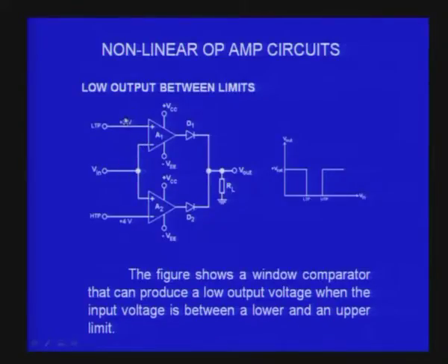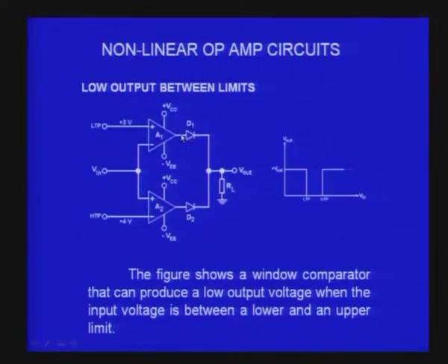Here this 4 volts is more than 3 volts, therefore it will be minus at the output in this A1, but minus here will make the diode open. It will not conduct, because diode has to be forward biased with a positive voltage on this side. Because it is a negative Vsat, the diode D1 is off.